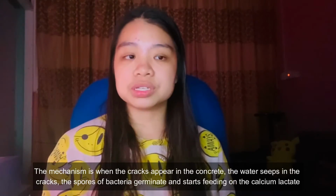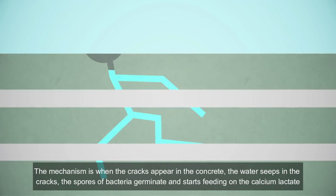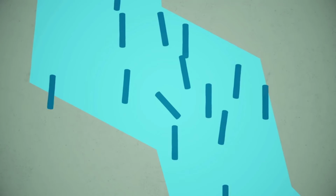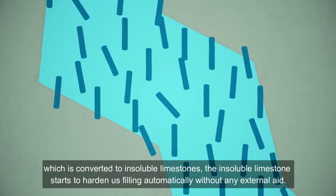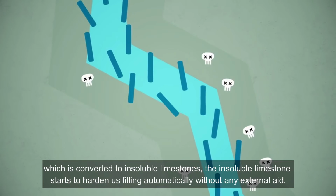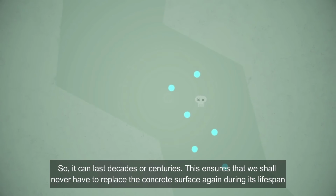The mechanism is when cracks appear in the concrete, the water seeps into the cracks and the spores of bacteria germinate and start feeding on the calcium lactate, which is converted to insoluble limestone, and the insoluble limestone starts to harden and fills the crack automatically without any external aid. So it can last decades or centuries.